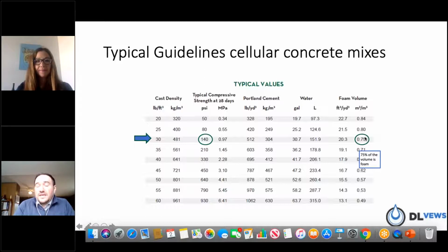But usually because of its sand content, it can become a bear to pump or gravity fill those voids when they're longer pipes. So I know from experience working with Snap-Tite that its pumpability and its ability to fill voids and get through to the other side of the culvert has always been a really good reason why they would recommend it in their design guide. And we just continue to grow with utilizing this technology.